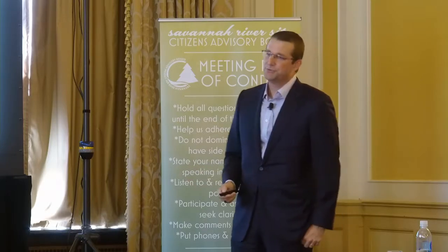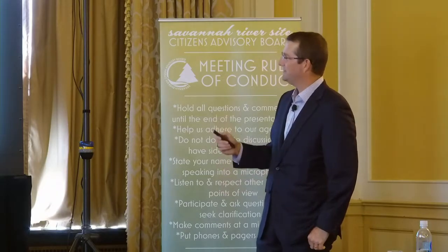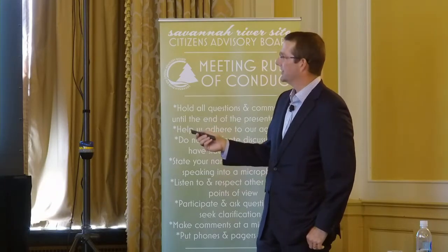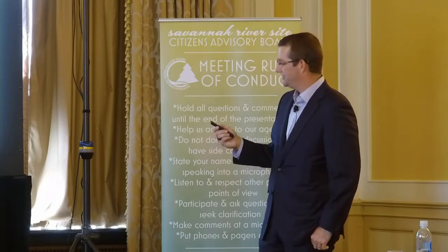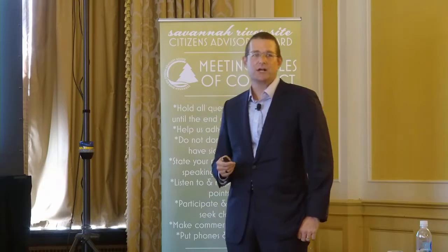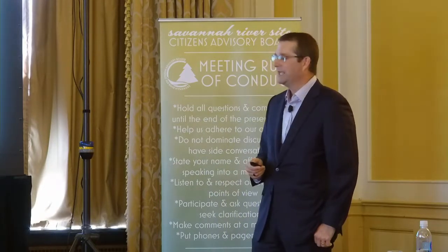So one of our residual challenges has to do with mixer wear. And I showed you a clean picture of the mixer a little bit ago. This is one that you can see has had some process use on it. And we have an issue with abrasive wear on the paddle tips that are directly upstream of our salt solution inlet. And that may be kind of counterintuitive, since I just told you that fresh saltstone has the consistency of chocolate milk. You're probably not worried about abrasion from your chocolate milk.